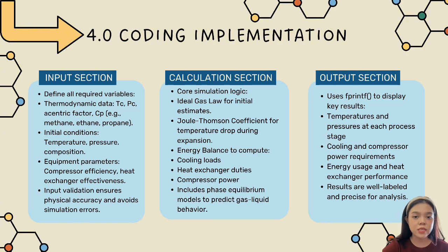Next is the calculation section where the core simulation logic is implemented. We use the ideal gas law for initial estimations, apply the Joule-Thomson coefficient for temperature drop predictions during expansion, and perform energy balance calculations to compute cooling loads, heat exchanger duties, and compressor power.